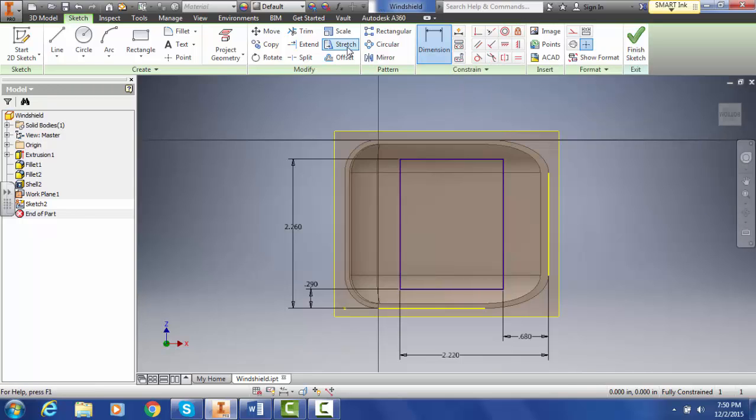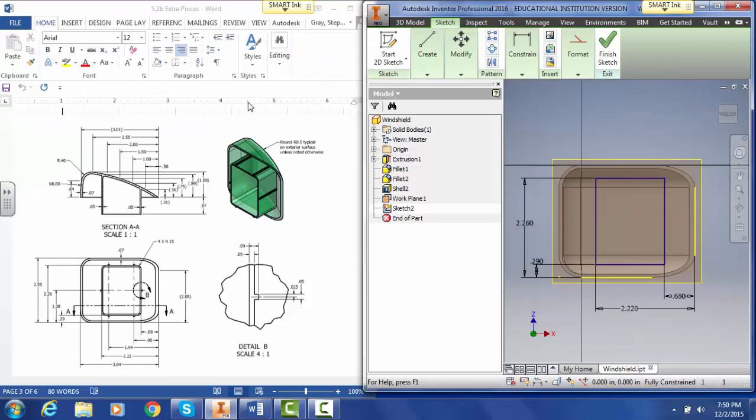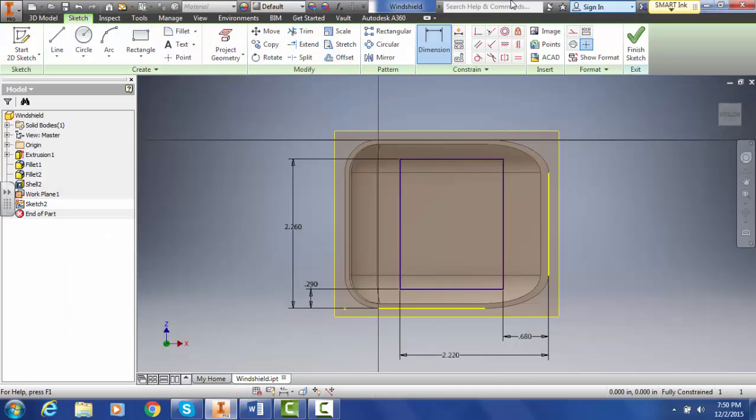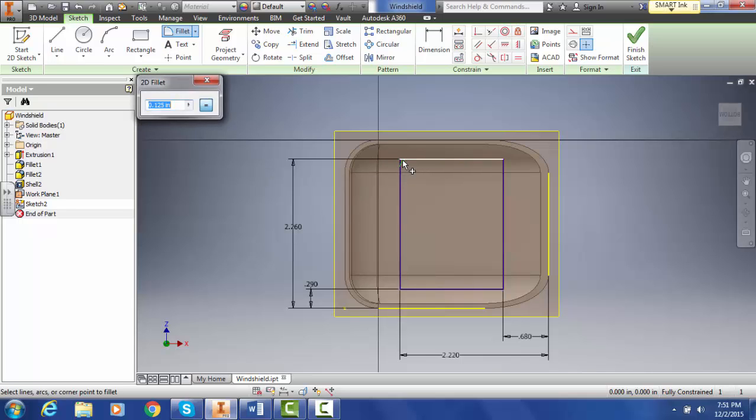Well, I'm actually going to use an offset tool right here. I'm going to actually fillet my edges first. So we're going to fillet those. These right here. Yeah, the radius is up here. It's 0.15. It says 4 of those at 0.15. So we'll go ahead and fillet these. So that gets done at 0.15. I really should have put my 0.15 in.